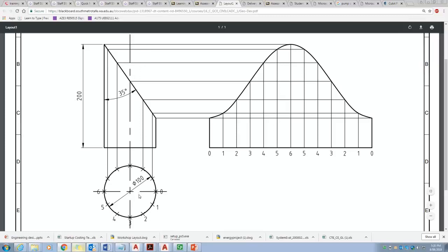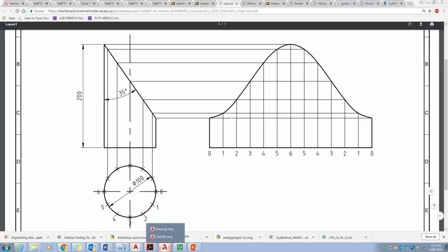So we'll use a couple of options in terms of arrays, multi-line text arrays. Then this is a polar array. We'll use a point option to insert the points with specific shapes, so in this we use cross shapes. We also have to do a lot of trimming as we extend horizontal and vertical lines to meet the array divisions on this side of the view as well. So this is the actual geometric development, which we will develop using the intersection points and apply a spline option on it. So come back to AutoCAD.